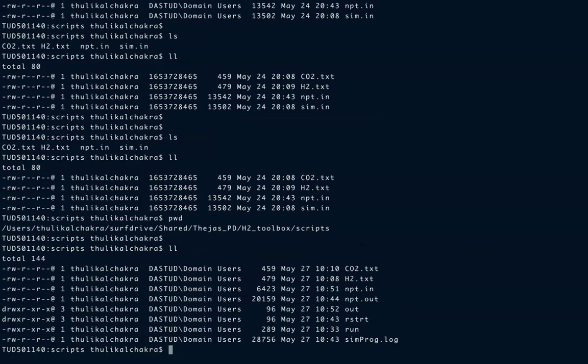What you need to describe in the input script is how you will initialize the positions of the molecules, how you're going to initialize the velocities, what's the size of the box, and what force fields you require to simulate a material or a gas or a liquid, and so on. These are the main features of an input script, and this is very crucial. If you define your input scripts in the right way, then the results that you extract can be reliable.